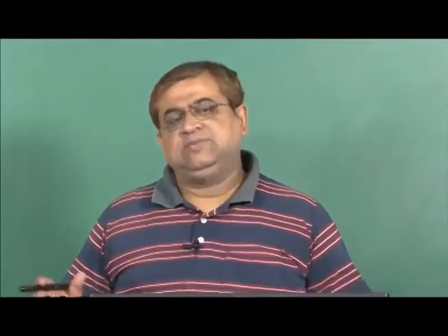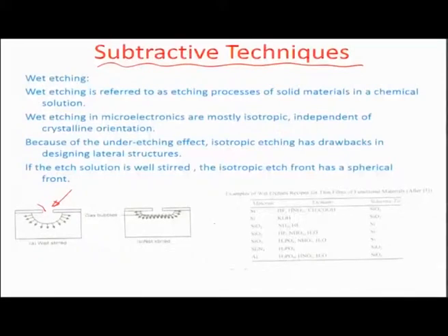So, for every chemistry that you are using, you should have a selective layer and a material layer, and this is how it has been illustrated here. For the different etchants which are used, for example, a combination of hydrofluoric acid, HNO3 and CH3COOH can work on an etch material silicon, but whenever there is SiO2, this becomes very selective to it and stops the etching process.